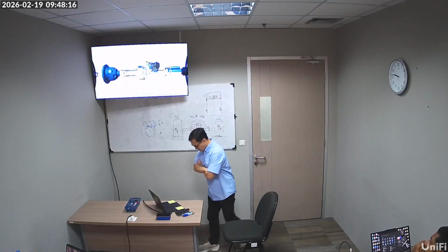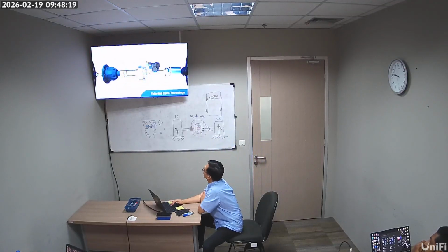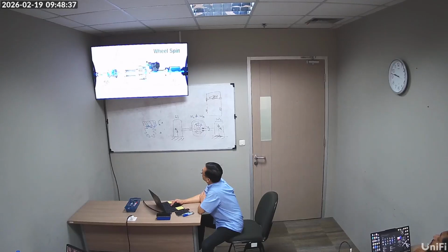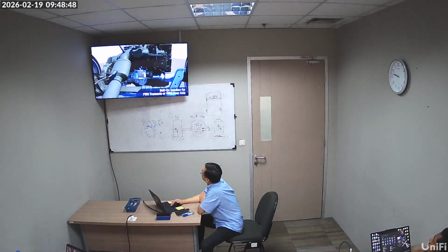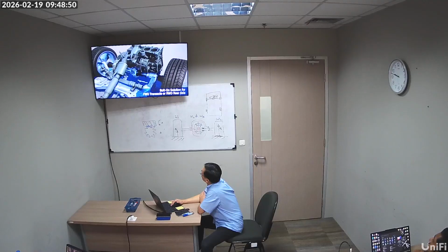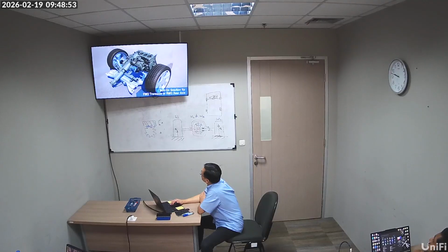Utilizing proprietary software to determine optimum torque corrections, it analyzes data from a number of sensors, calculates the required traction, and distributes torque to enhance handling. The control unit monitors vehicle parameters over the vehicle CAN bus to gauge when a wheel spin is imminent. A signal is then sent to the electric motor, which spins up and drives a ball ramp through a gear ratio. The ball ramp loads a clutch pack to limit the speed difference, transferring torque to the wheel with good traction. This technology is a bolt-on solution for any front-wheel drive transaxle or rear-wheel drive rear axle.